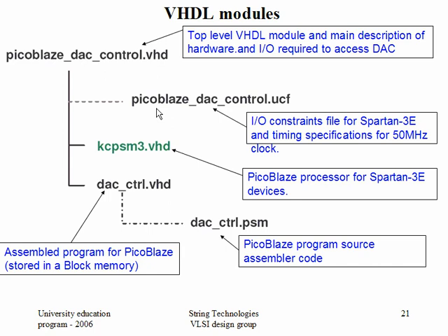Okay, you want to optimize one specific path which you feel is the critical path. That has to be given the highest priority to improve the speed. So that is what is called timing constraints. Pin constraints, timing constraints, area constraints, all these things we give in a file called the user constraint file, the UCF file. Okay, so that is a UCF file.